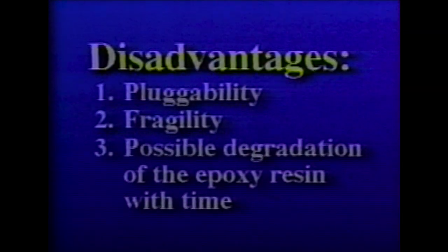During backflushing, the media is lifted and fluidized, and there is no top support on the epoxy cake to hold it down. Because of this, the cake can crack at the beginning of the backflush cycle, and there is the possible degradation of epoxy resin with time.